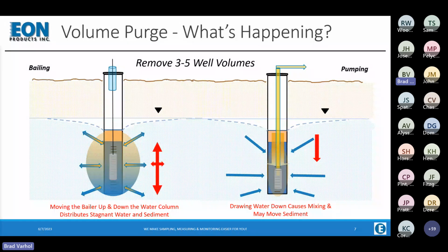But you know, there's another adage, and that is that water follows the path of least resistance. And the least resistance in most wells is vertically. So as we turn on that pump, we have a very good probability of pulling the stagnant water or some of it and blending it or mixing it with the aquifer quality water. And of course, again, we're not representing the true quality of the aquifer. You can see that happening because there's drawdown at the top of the well that's indicating the pressure differences. And of course, that's driving this stagnant water and groundwater mix.